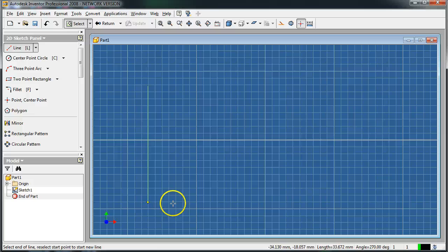Alright, so I have the first line created, and I'm going to drag across until we see the perpendicular signs that appear up on the screen. Those perpendicular signs will tell us that the first line segment at the bottom intersects at a 90 degree with the top section of that line, or the second line. Click again, go up, and you're going to see an auto snap feature, which shows us that not only are these two lines going up, the vertical lines, parallel to each other, but we're also going to know that if we create an endpoint right where the crosshair is at this time, you're going to then be able to make a rectangle using what you have so far in that part of the geometry.